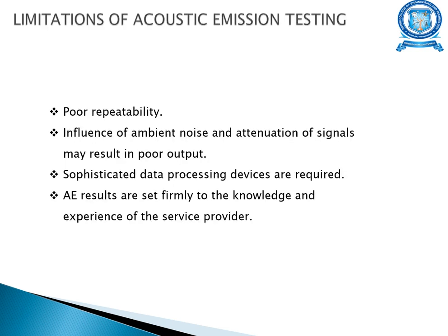So that is the advantage, and it also has its limitations. It has poor repeatability, and the influence of ambient noise and attenuation of signals can result in poor output. And data processing is sophisticated. Acoustic emission results are tied firmly to the knowledge and experience of the service provider.